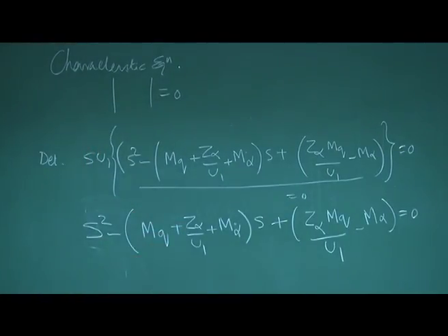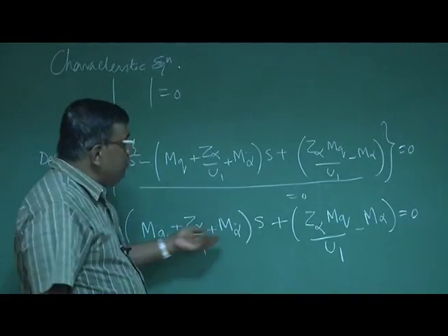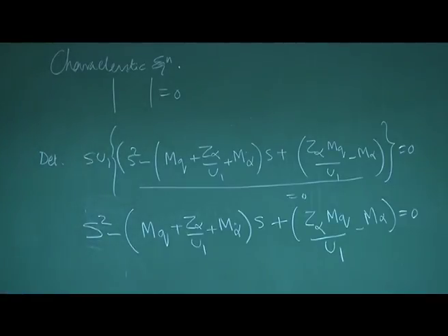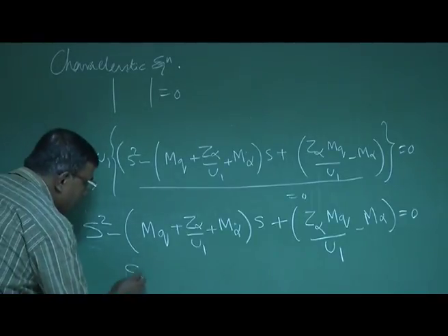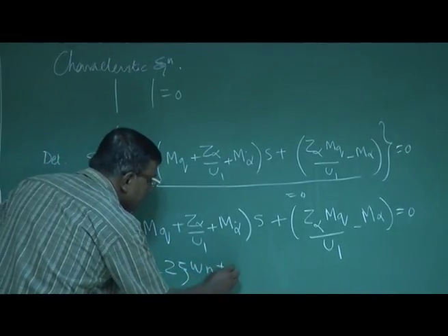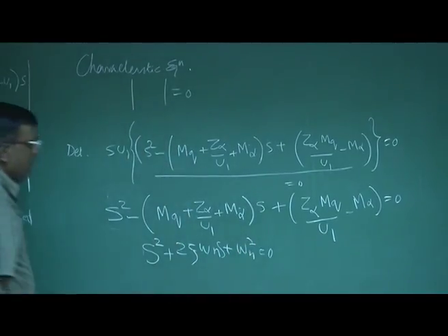Would you see that when I do a short period approximation, we have got an equation which is a second order equation, and we are very much handy in handling this equation because we know if I want to find out damping ratio and natural frequency, I have to only compare it with this form which we have already derived. So now if I compare, what do I get?